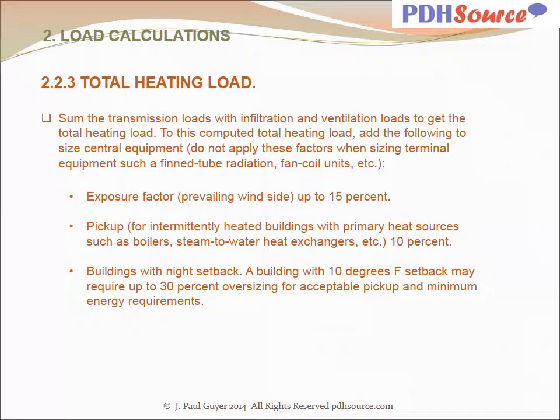And that pickup additional load might be in the vicinity of 10% or something like that of the calculated load due to transmission loss and infiltration and ventilation.